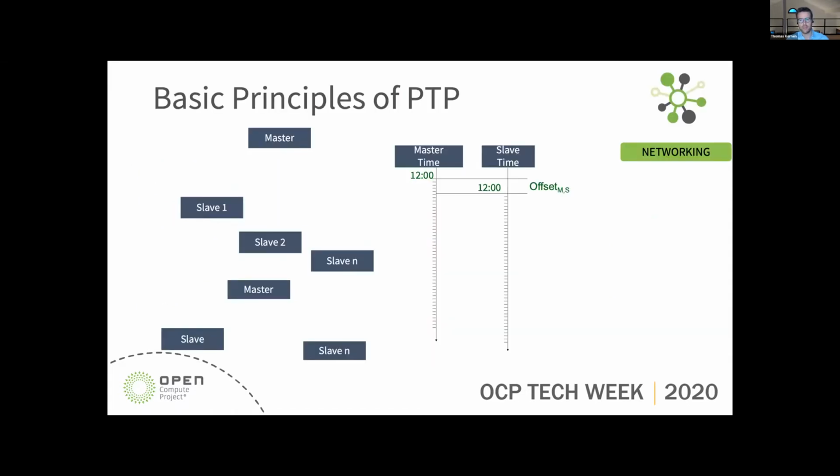So just to get everybody onto the same page, because Precision Time Protocol, IEEE 1588, is not the most common protocol on the block, I'm just going to run through the ideas and the concepts of how this PTP works. We have, assuming that there's been an election process and that a so-called master, i.e. a reference clock with a time source, is available, that master will start distributing messages over the network. And the first type of message that it sends out is what we call a sync message.